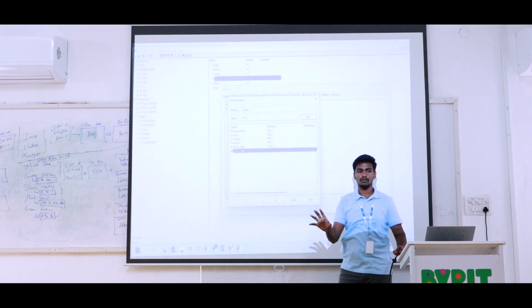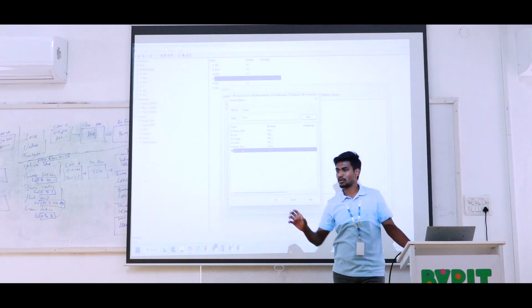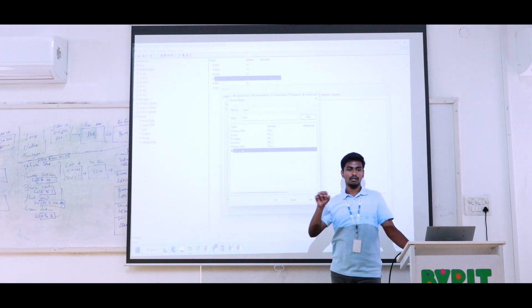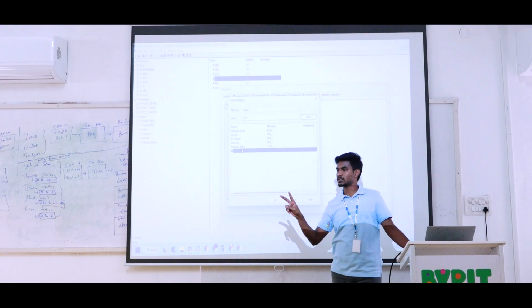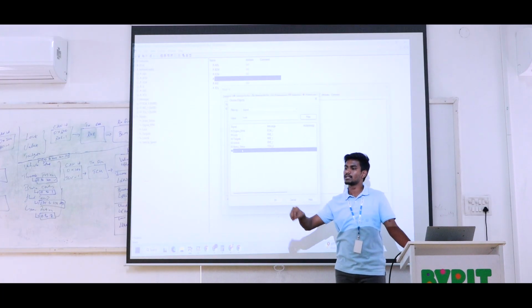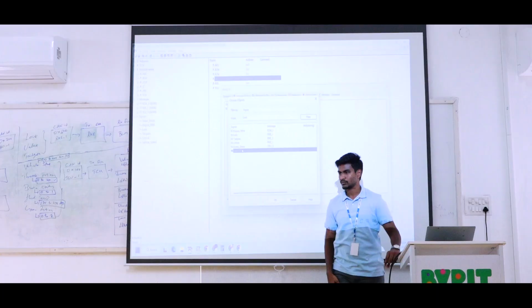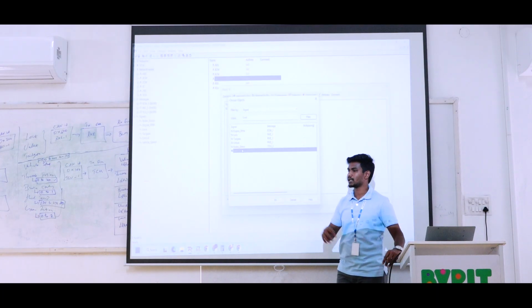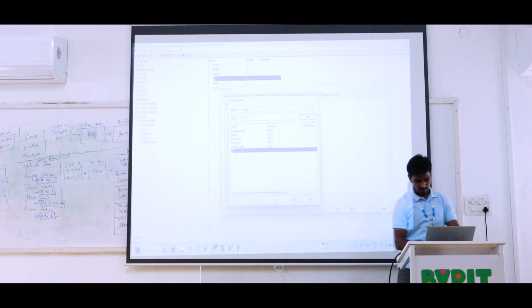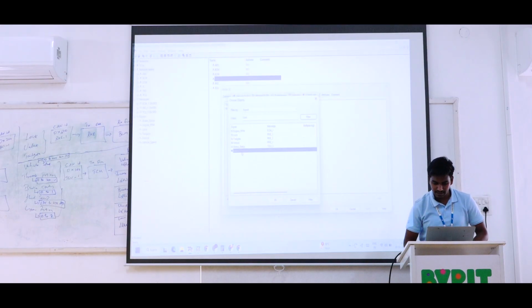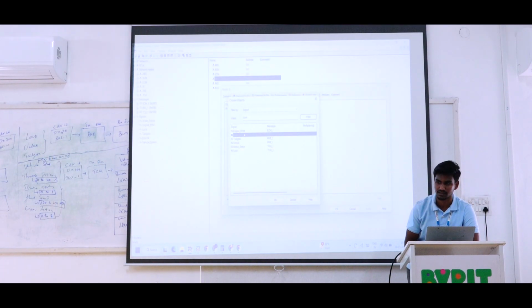For example, now our car has ultrasonic sensors for the reverse parking system. They are using, for example, only two sensors at the back side. So the sensor values will be taken, and then you can give them to separate ECUs. So the same value can be taken by separate ECUs. Just a minute. So I can select the lock TCU_1, which means I am not selecting the RK message. I am just selecting the TCU message. Okay.